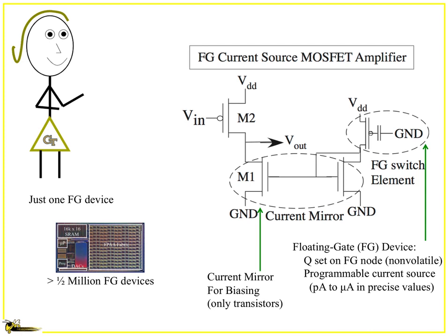And you go, well, okay, this is just what we get with one floating gate device, where I can actually get a floating gate element that I can set that current 6 orders of magnitude or more in current based on just programming the charge. So this is like a huge range in, say, frequency responses, which is one of the things I'm going to care about. And I have the current mirror that allows me to do this. That structure then also allows me to do some other neat things too, right? Like deal with any offsets, which is another major problem. And so that can get out the mismatch.